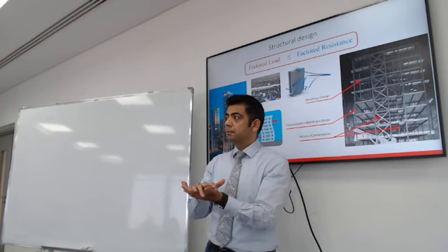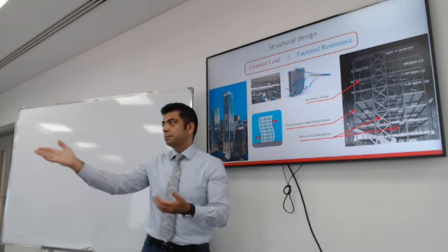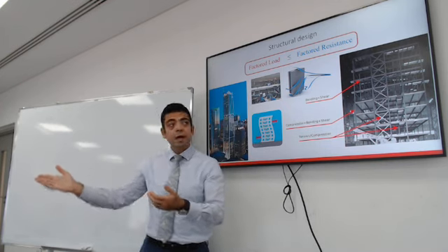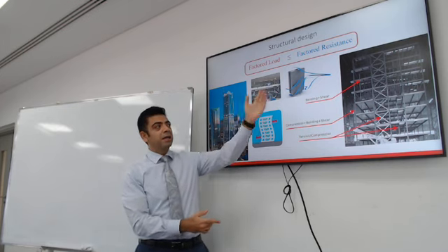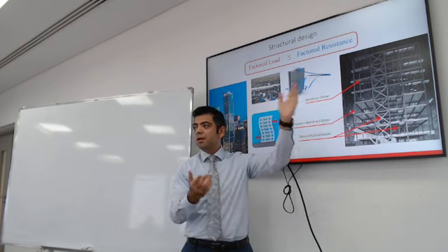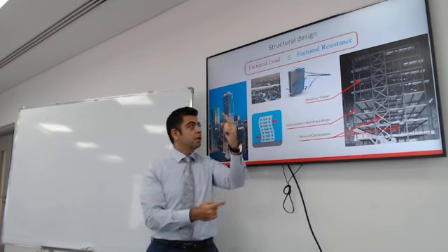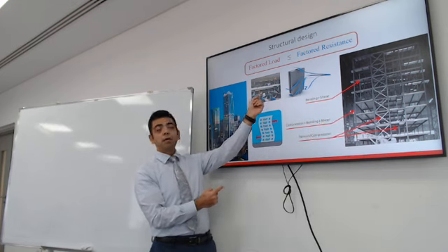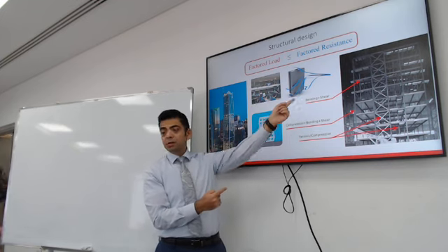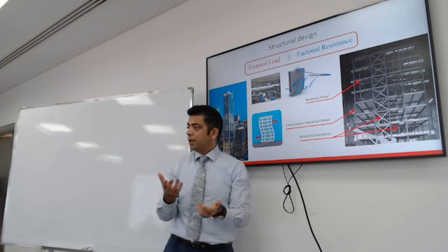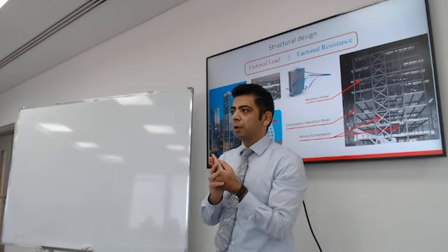The live load that supposedly should be on the beam or the structure. Absolutely. So you think of, okay, the building is going to look like this. It's made out of structural elements. First, figure out the load. The load comes from the weight of the people, the self-weight of the structure, wind load, seismic load, earthquakes, and all these types of loading. All right.